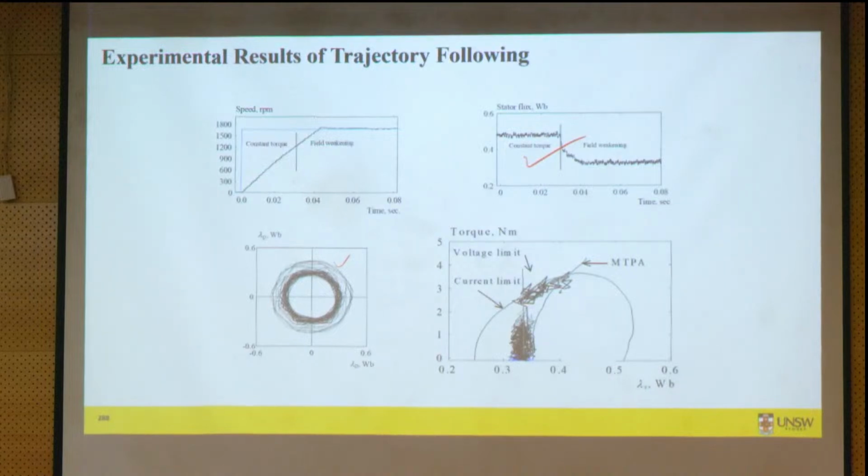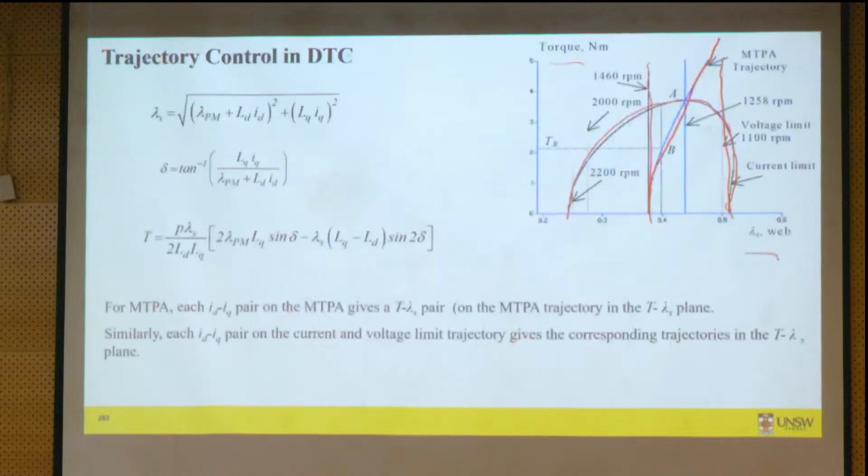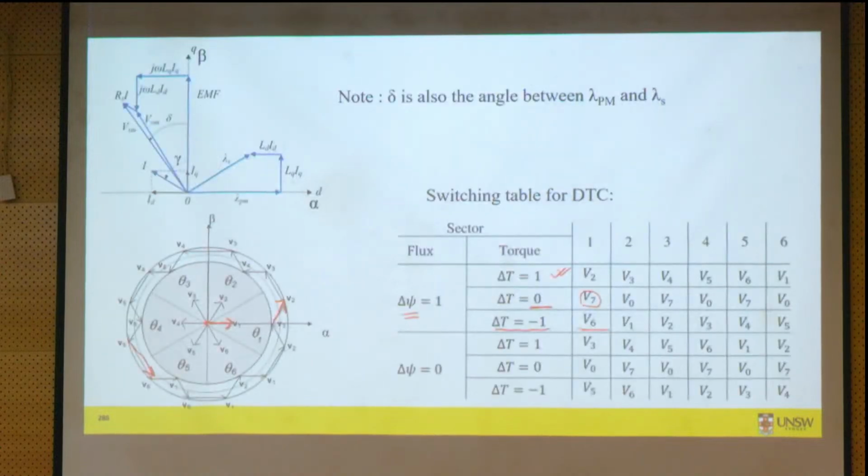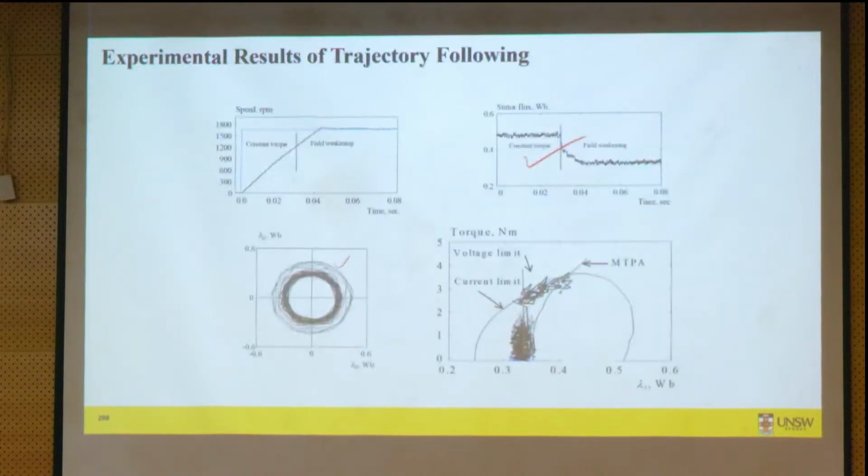Yeah. So this is because you can see here the voltage vectors are varying in a kind of band, a hysteresis band, right? And we are using hysteresis controllers, right? So because of that, you do not get a smooth circle. It varies because these are instantaneous values. You can't see a smooth circle.